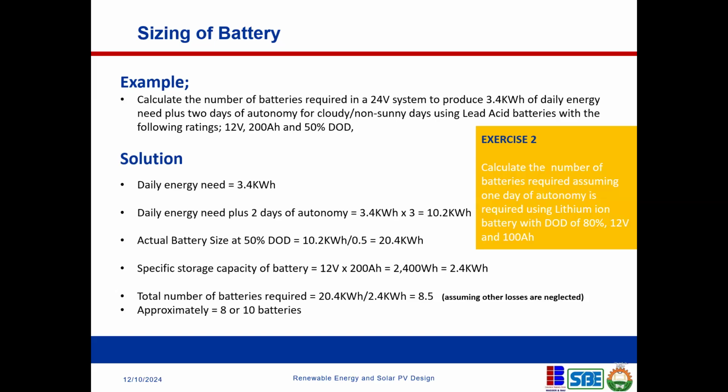It's just science. That's why battery manufacturers will tell you that if the battery lifetime is 6,000 cycles, they will tell you the temperature, usually 25 degrees. What that means is that if your installation is maybe 35 degrees, where you install those battery systems, then you should expect more losses and fewer cycles.